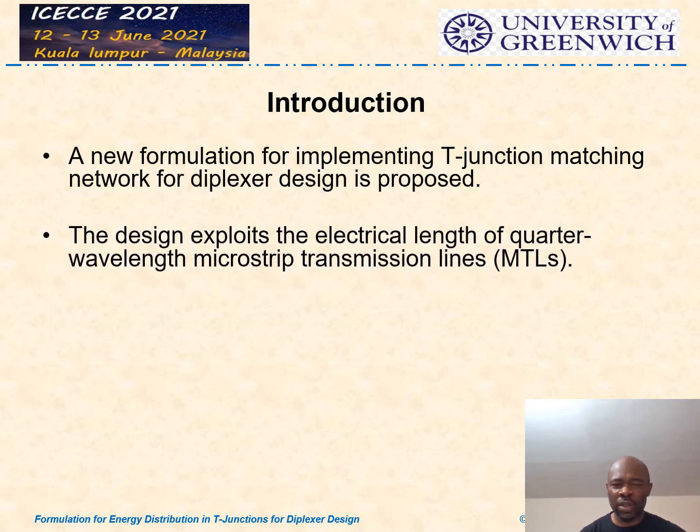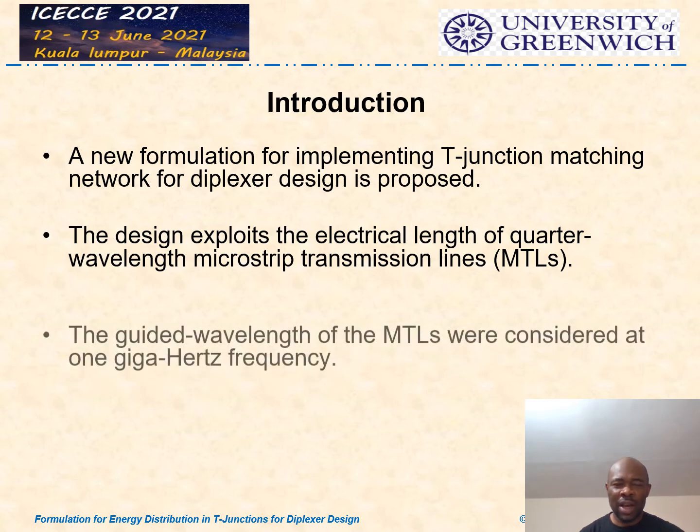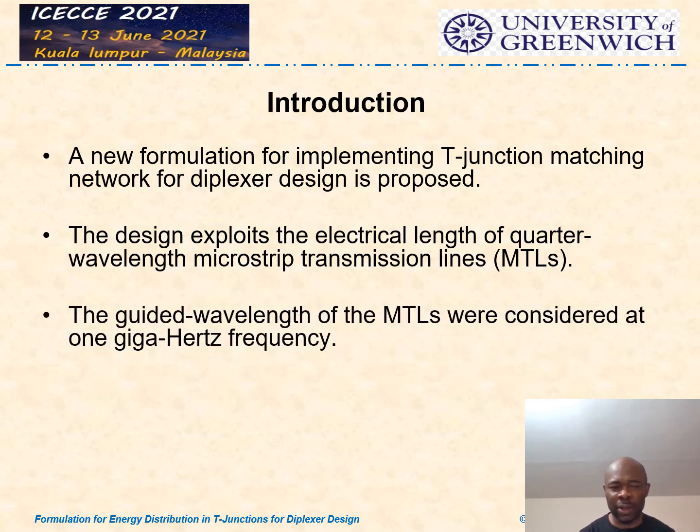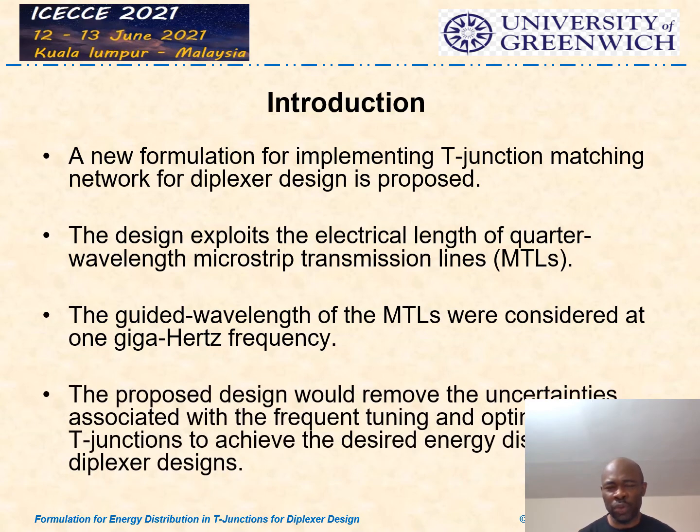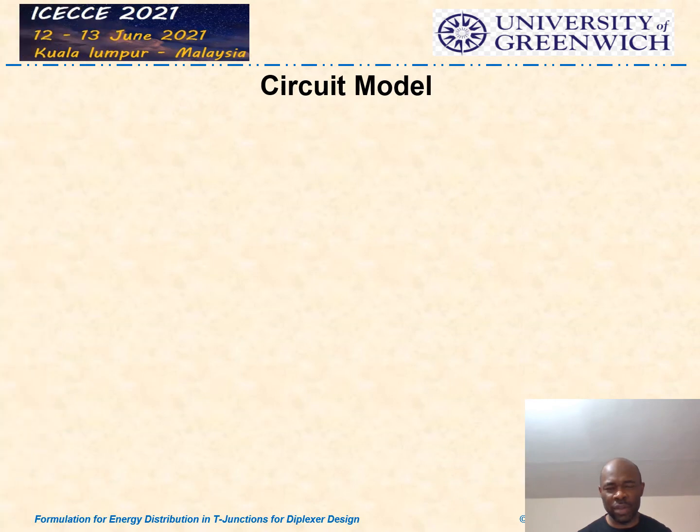We'll be exploiting quarter wavelength microstrip line in this investigation. We'll be using 1 gigahertz frequency to implement the microstrip line. So that's basically what we'll be looking at today. I'm going to start with the next slide, which is the circuit model. How did we design this?